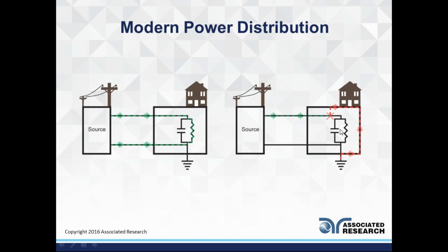Now, if some sort of fault condition were to occur, this is where your grounding comes into play, or your ground circuit. That fault current will be caught by that ground and be delivered back to your source. That way it's not floating on top of any chassis or metal handles, anything exposed to yourself or users. So it mitigates the chance for shock.